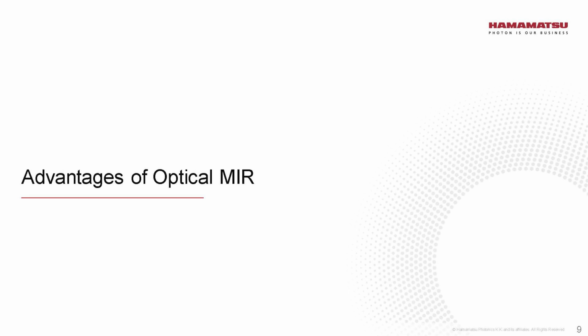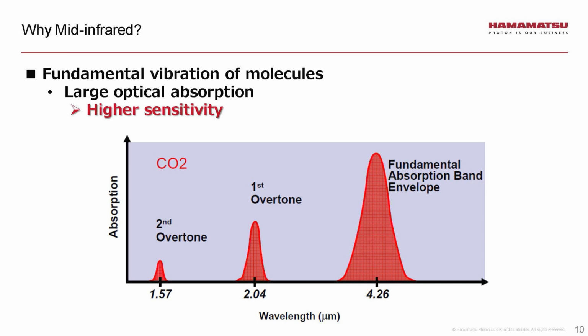So diving into the mid-infrared itself, for those who may be familiar with optical techniques to start, I mentioned carbon dioxide before. You can measure carbon dioxide using near-infrared wavelengths, so around 1.5 micron or 2 micron, or 1,500 nanometers or 2,000 nanometers. However, looking here, you can see the absorption characteristic is so much stronger in the mid-infrared. If you have stronger absorption characteristics, and in this case it's by orders of magnitude, you can achieve orders of magnitude higher sensitivity in your detection systems.